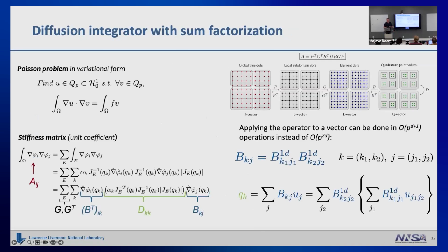You basically saw this slide in the first two talks today, which is just introducing some factorization, which is used in partial assembly. Instead of a dense matrix assembly, you can just do a series of 1D contractions. This reduces the complexity of the operator multiplication. And we also use this idea in matrix assembly.